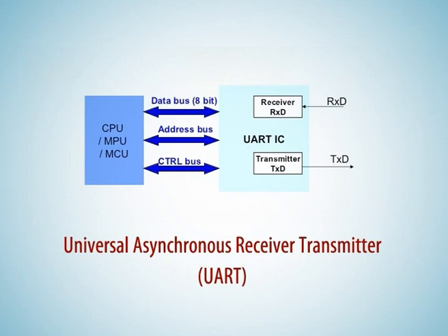UART is a hardware block or a circuit implemented in an integrated circuit, or IC, to implement a COM port. It is an acronym for Universal Asynchronous Receiver Transmitter. This block carries out all desired functions of converting parallel data into a serial bit stream and vice versa. All the logic mentioned in asynchronous serial communication in section 2.2 is implemented by this IC.